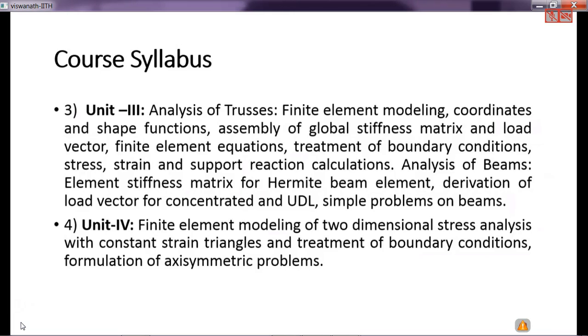Can we use the same symmetry in our finite element formulation, is the question. Yes, we can use it. Now, why do we have to use it? If we don't use this symmetry condition, the problem is to solve a three-dimensional structure. You know that the cylinder is loaded axisymmetrically, the geometry is also axisymmetric. Then why would you want to solve a problem in a higher sense when you can solve it simply? How can you solve it simply? If you know how to deal with axisymmetry formulation.